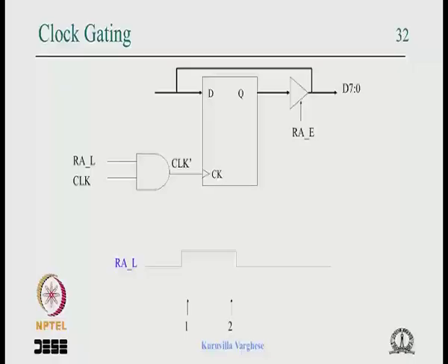But mind you, there is one thing I should be mentioning here. It appears that it is enough to avoid this glitch problem if you push this gate signal, the enable signal, here by introducing certain delay. Suppose you introduce 7 nanoseconds and it appears here.